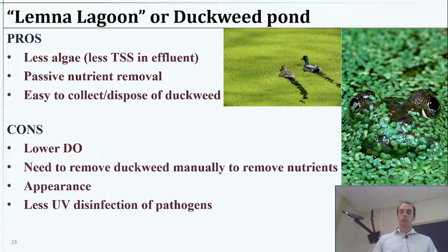And then in general, there's probably less reduction of pathogens because you don't have as much UV light naturally coming in and slowly disinfecting. The UV light that we would get in a normal pond is not going to travel very far, and it's not that type of UV light. That's UVA, maybe a tiny bit of UVB. That's not direct germicidal like our UV dosing systems. So it takes a lot over a long time, basically. It'd be like trying to kill microorganisms by sunburn, right? You'd have to have quite the sunburn to kill a microbe, right?